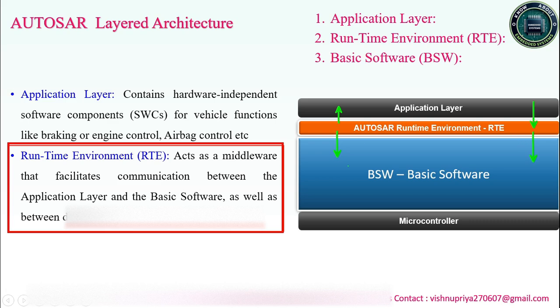With the help of the runtime environment, we will be able to connect to the BSW base software or vice versa as well, and it will provide some of the interfaces and APIs. So RTE will provide its own application interfaces, and RTE will also provide some of the global variables interfaces in order to connect base software and also application software.